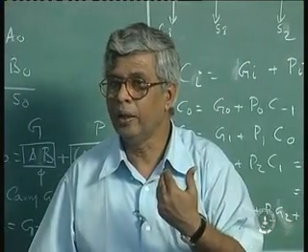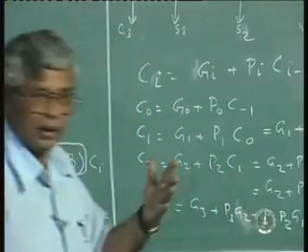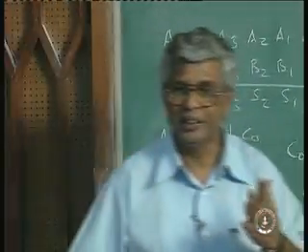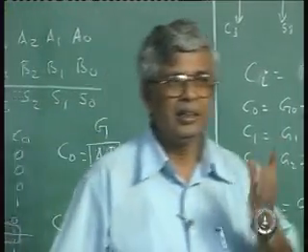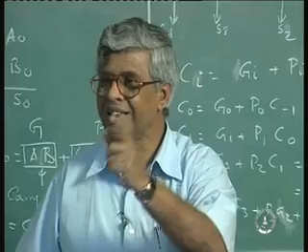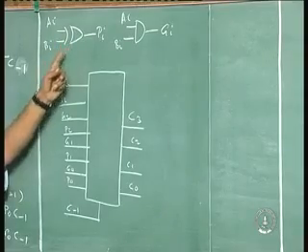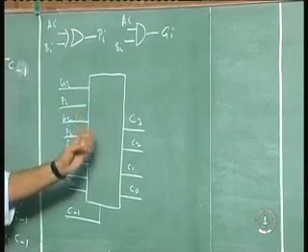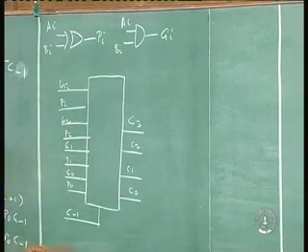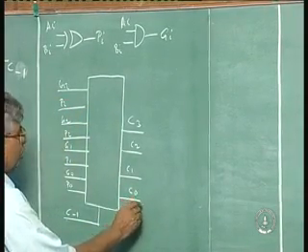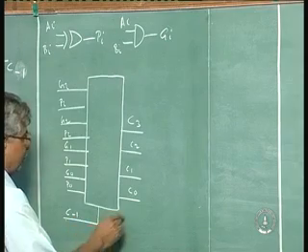What is the sum of the full adder, if you remember? S is A exclusive or B exclusive or C. Since I have A exclusive or B already and all these C's, one more level and I get the sum. So P0 exclusive or C minus 1; the first stage of course does not need it.